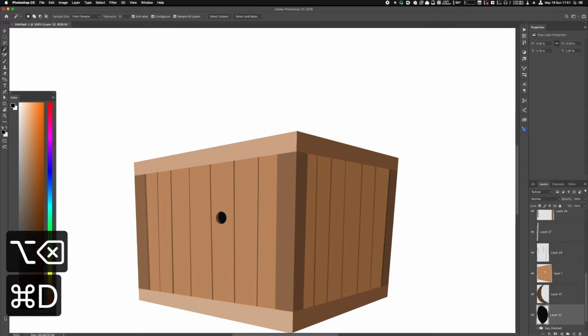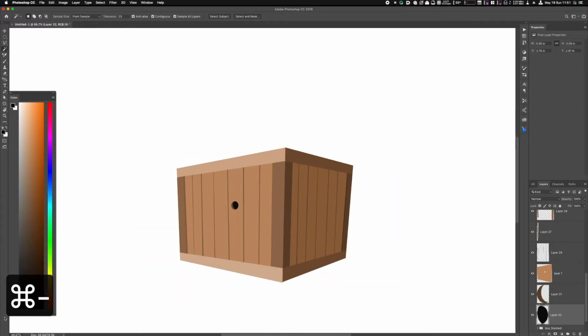So something's in the box. I've got all the basic shapes configured for this particular object. Next, I want to add some texturing information. Yes, it looks like wood, or it gives the appearance, but I want to make it more obvious. So I can switch now to my freeform lasso tool by holding down Shift and L.